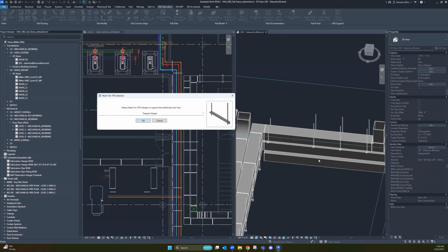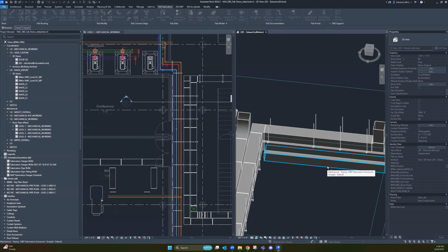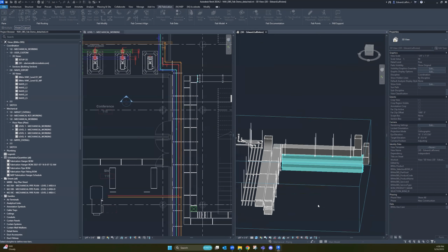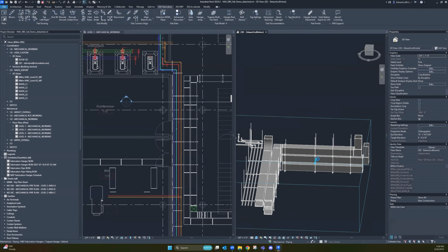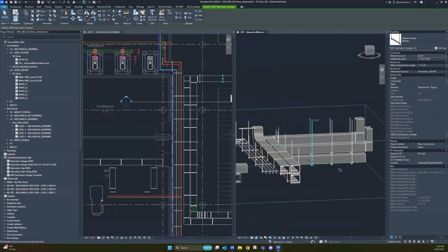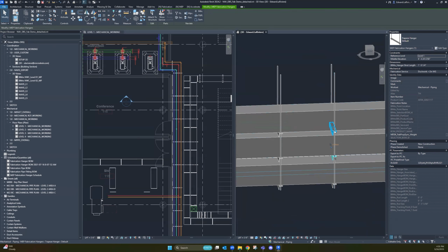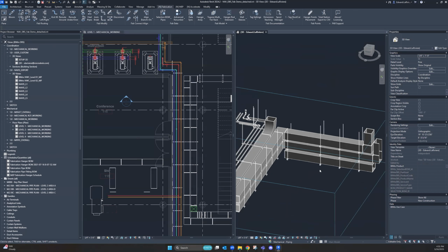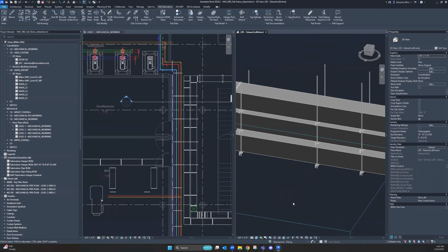That way we have one rod that encompasses the full length, but we can still show that angle iron for each additional tier we're working with. So I'm going to use that same trapeze hanger, click OK, and choose the other tiers I would like to work with. Once we click Finish, we'll find that it's able to extend that first hanger down to the bottom. It then adds in that individual strut for those other 2 levels that we need to work with. And we're now able to use one rod to support all 3 racks while still showing those individual angle irons for the other levels.